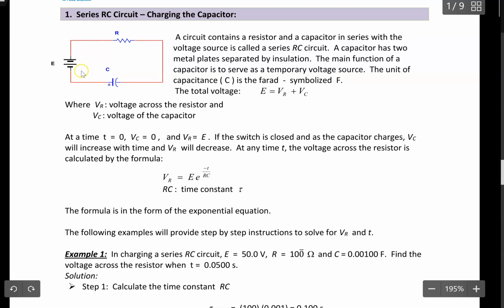At the time t equal to 0, the switch is open. Then the voltage across this capacitor is equal to 0, right? Because you haven't charged it yet. If I close the switch, I get current going through the circuit. When the current goes through this capacitor, it starts charging the capacitor, and I create a voltage difference across it. So let's talk about voltage in this case.